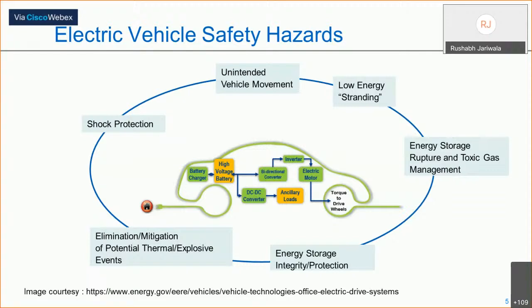And the other thing is, if either the inverter or e-motor gets powered due to some internal fault, that can also start propelling the car, because the HV battery pack is always live.